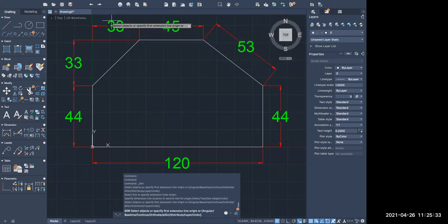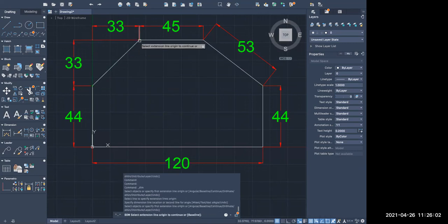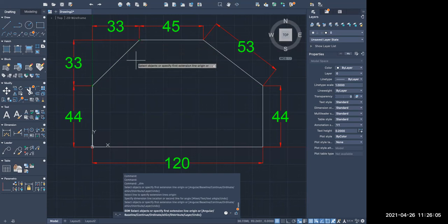But your question is why I am giving this vertical and horizontal and how I am switching between inclined and vertical, horizontal. Am I correct? Yes, sir, correct. So how this inclined is coming is now clear to you. Automatically, if you click on those, you will get the inclined dimension. If you want to give a specific vertical or horizontal, then you need to carefully select those 2 points and then you can give the vertical or horizontal dimensions between 2 points. Basically, it is nothing but between 2 points.